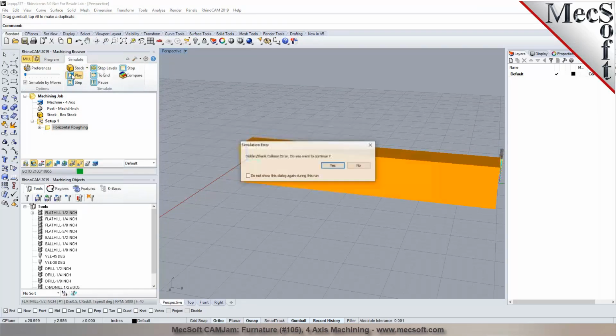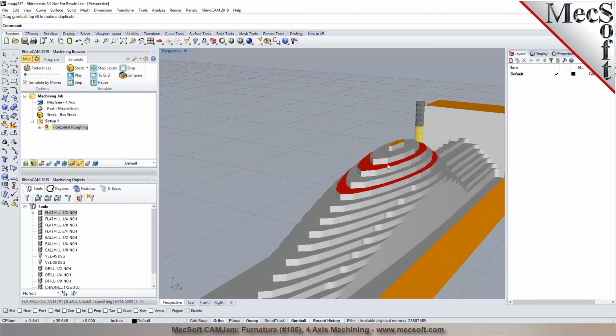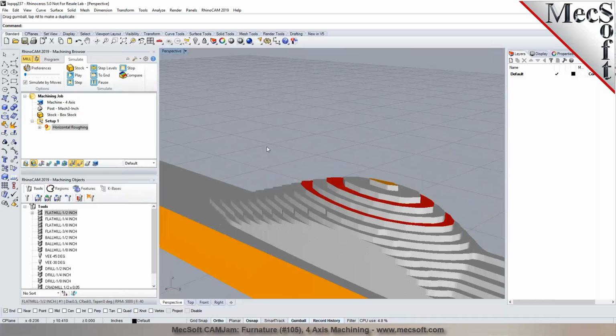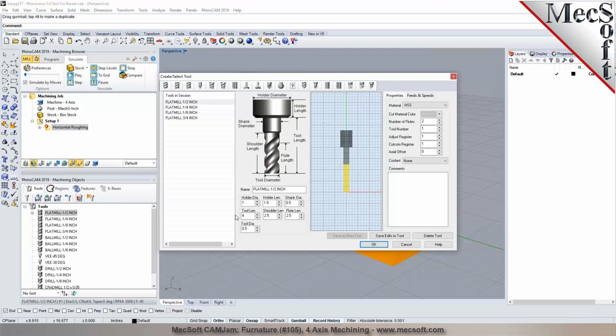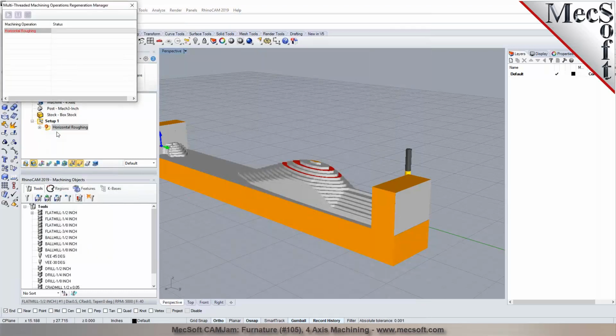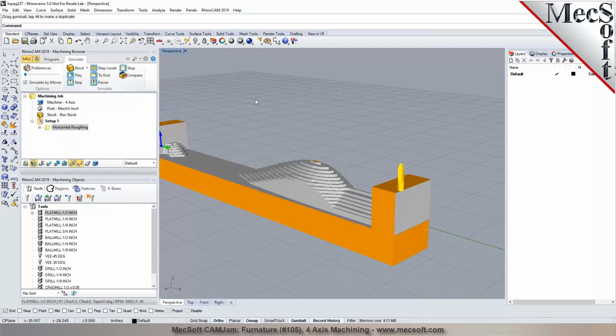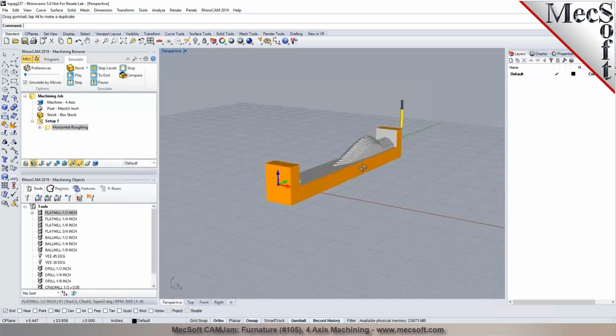So now when you go ahead and hit the play button, it says there's a holder shank collision detected because my tool flute length is only set to 2.5 inch, and you can see there's just the holder shank collision that you're seeing right there. Fine. So I can always go back in here and update my tool definition. Say my tool is about 6 inches in length, shoulder is about 4 inches. I can change the flute length also to 4, save it to the tool, and then I just go back and regenerate this tool path in here. Right click and regenerate, and it'll check for, again, holder shank collisions, and then identify if there is any collision detected. So now we don't see any collisions, as you noticed it.